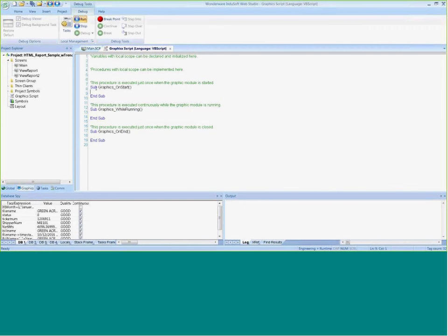And here you can put VB script in when any screen opens, like when your project first starts, while there's screens open. So then you can put code in here to determine what you want to do. If the time of day equals such and such, or if it's the end of cycle or something fails, then you could do whatever emailing or reporting or toggling of tags that would then fire off something else.